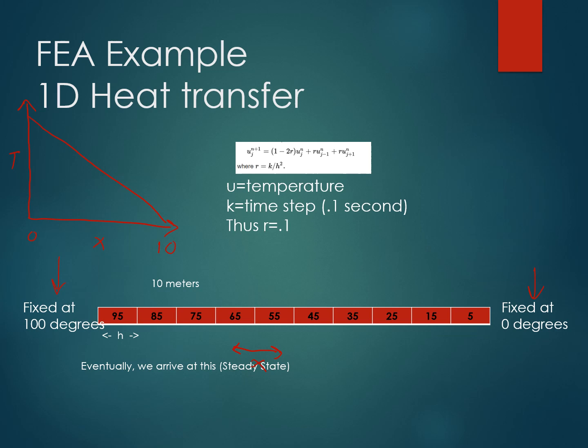Now, when we deal with more complex airflow and fluid flow, we'll usually end up getting some oscillating patterns and some more complex patterns because we've got much more complex geometry. And that is a very simple one-dimensional example of how a computer is going to translate these differential equations into algebra to determine these complex fluid flow, complex heat flow simulations.